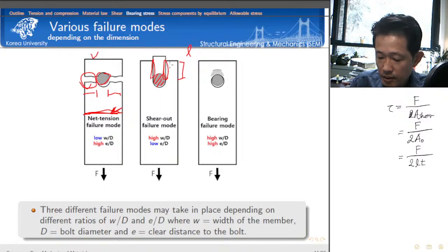This is similar to the failure criterion we just discussed for tensile failure. If the shear stress is greater than or equal to the criterion, typically F with subscript tau, which represents the shear strength, we consider it in the design procedure.